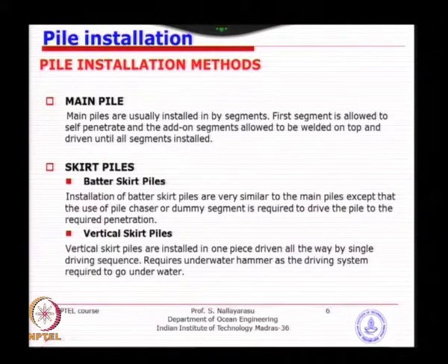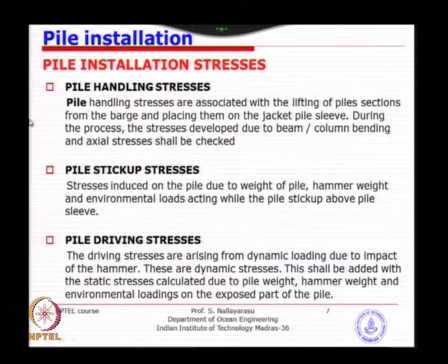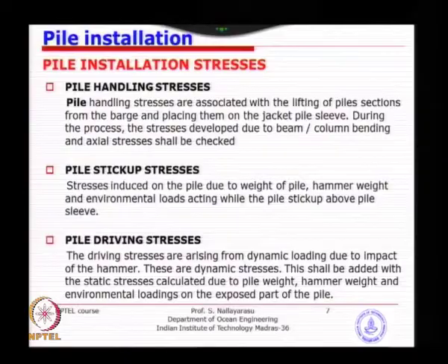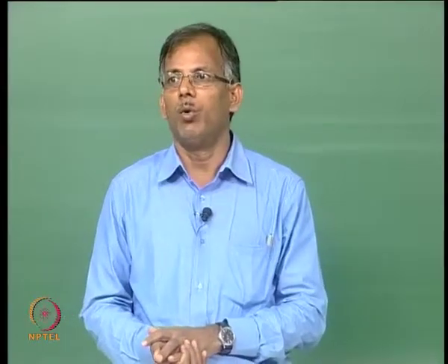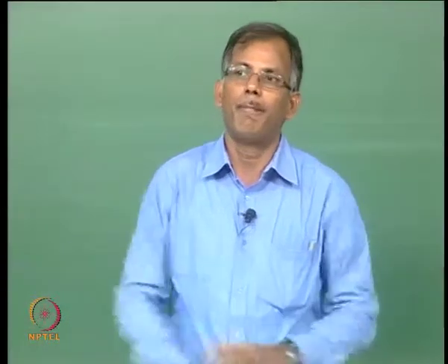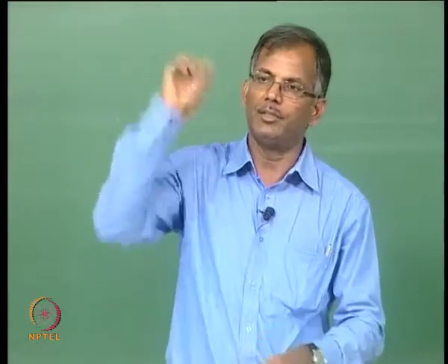So, main pile, skirt pile, I think by this time you have a clear understanding of how it is going to be installed. Vertical versus batter, the reason why we cannot provide support in the batter piles. So, what we are looking at is the pile handling stresses. Now, you can see the main pile will be a smaller segment, skirt pile will be one big length. Imagine if I have to lift 100 meters of length of pile in one lift.